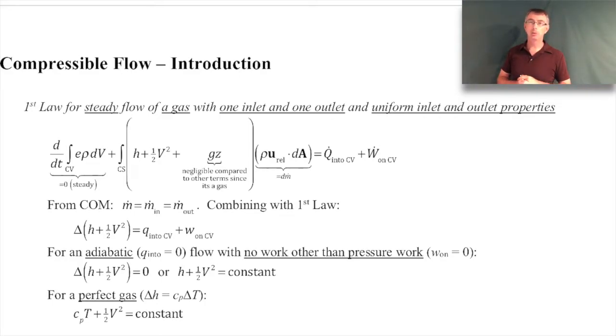So we're only going to consider gases in this section of the course. And by the way, when you deal with gases, if you think about Bernoulli's equation, you had that pressure term and a kinetic energy term and a potential energy term. That potential energy term is very, very small in comparison to the other two terms when you deal with gases because the densities are so low. And so we'll make use of that assumption here since we're dealing only with gases. So that'll show up in just a moment.